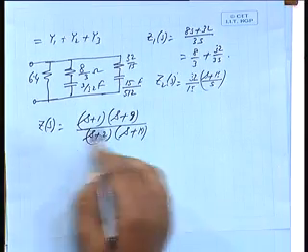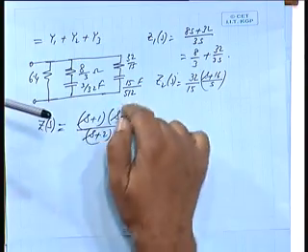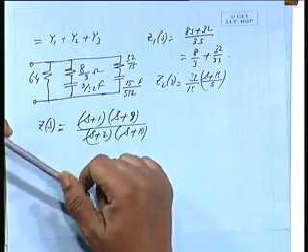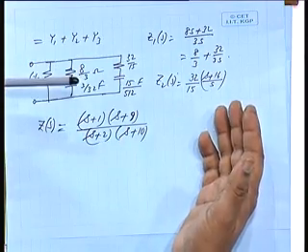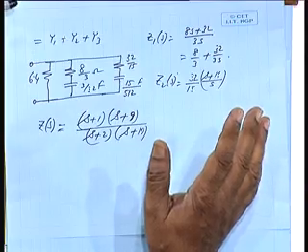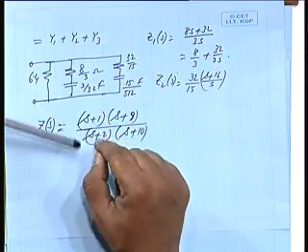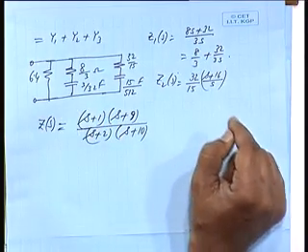Will it be an RC network? Why? Zero is coming close. Poles and zeros are alternately coming. Zero is close to the origin. So, this is not realizable by RC. We have observed for an RC network, the pole will be closest to the origin. The first one will be a pole if you calculate these roots. Is it all right?